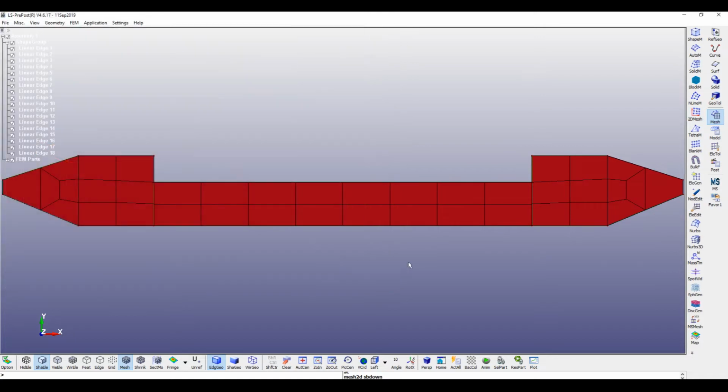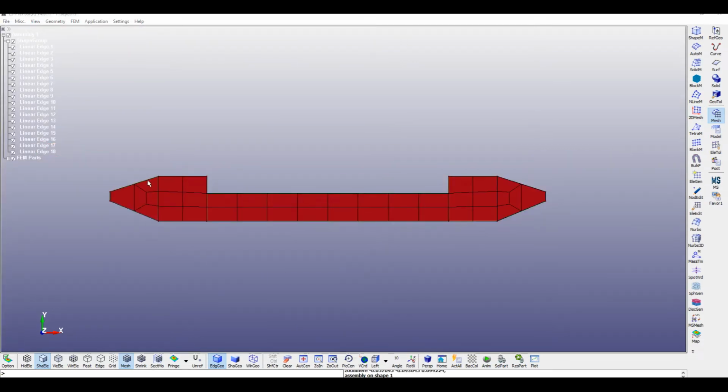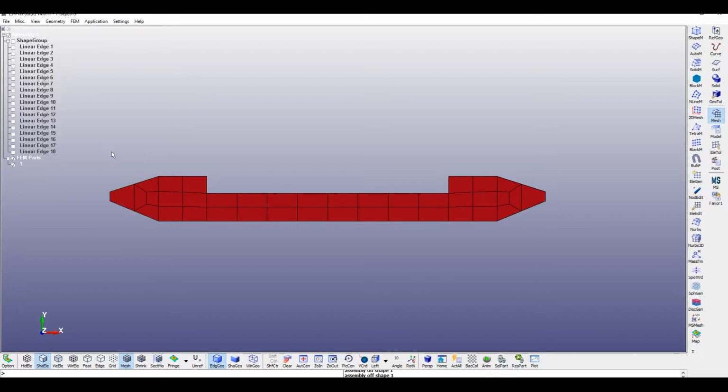I have to exit this one. Now this is the sectional view updated with meshing in LS-DYNA. After generating the mesh, it creates a new part here, a finite element part. So after creating the part, there is no need for the geometry file further, so I deselect this one. Later I will delete this one.